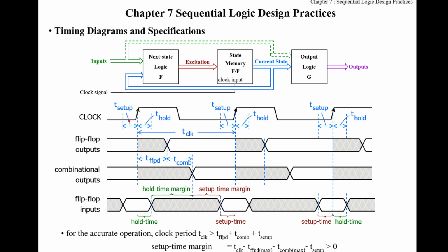But if the frequency of the clock increases and becomes maybe something like this, and the clock ticks here, it's not okay, right? It's not okay because the signal is not available now. There is something in this duration of time.